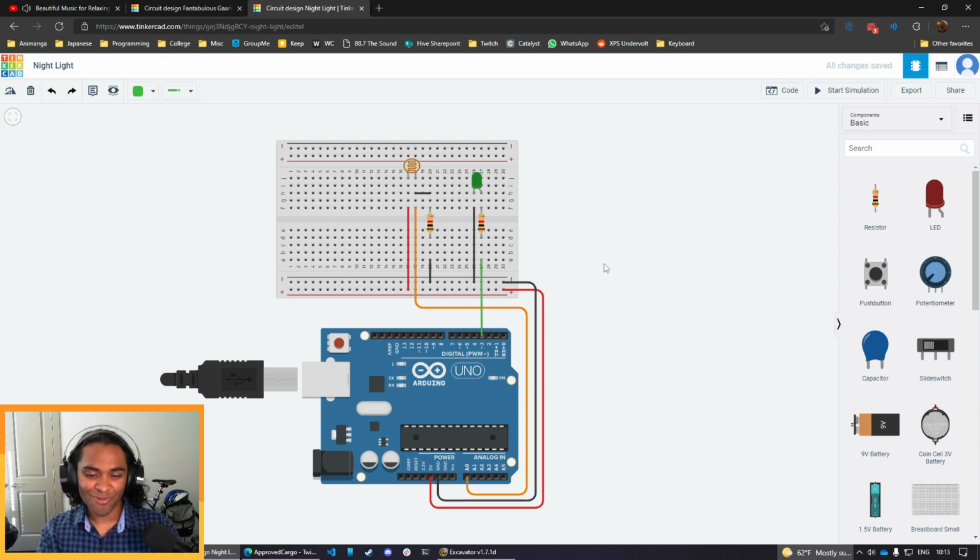Now, obviously, in real life, there is an infinite amount of voltage values between 0 and 5 volts, right? You can go decimals. You can go 4.5. You can go 4.0005. And that might not be accurately represented by the digital scale, but it's the best we can do in this situation. So 0 to 1023, we have 1024 possible values. That'll be important for later when we start coding stuff.